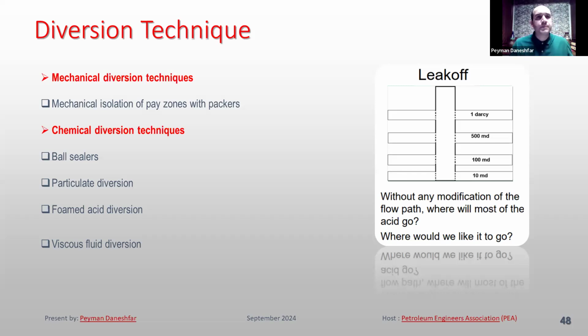We use all of them, but just beside our main acid. Normally we use a mineral acid for the acidizing, but for deep penetration, some references say you can use acetic acid or an organic acid, but I think the cost of the operation will be more.